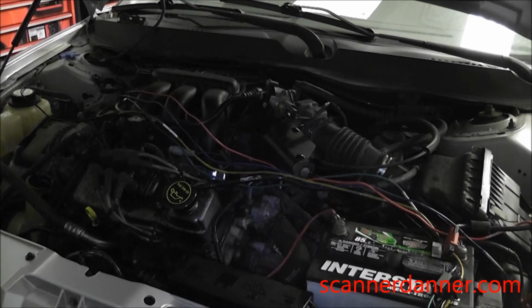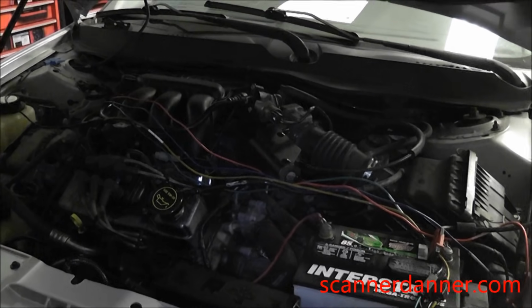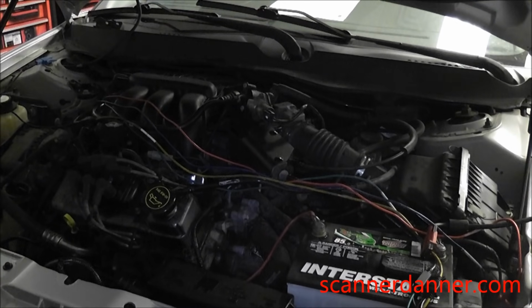And I know some of you are probably going to chime in here and say, why don't you do inlet and outlet temperature tests on the converter? And I have to be honest with you guys, I don't like that test. I just think there's too many variables to it. I mean, what if you have a clean running engine, it's running perfectly? Is your outlet of the cat going to be hotter than the inlet? That's the theory behind it. The outlet should be 10% hotter. It's just, there's variations to that.